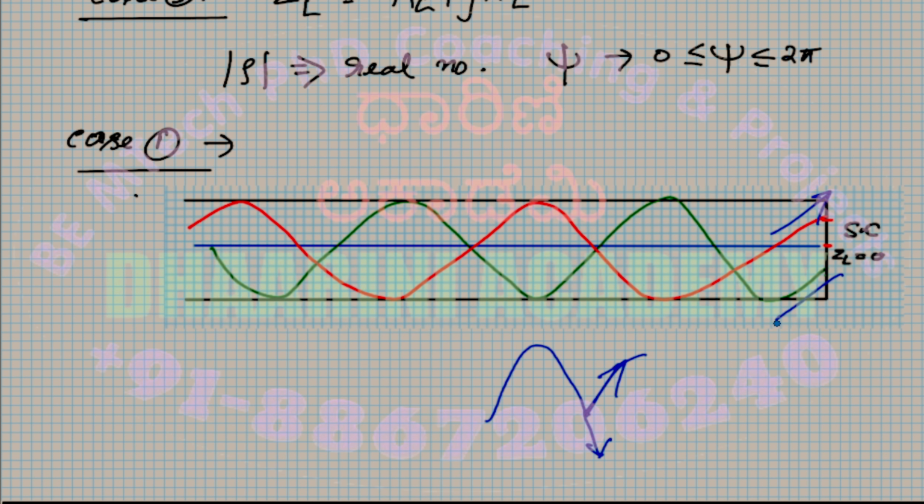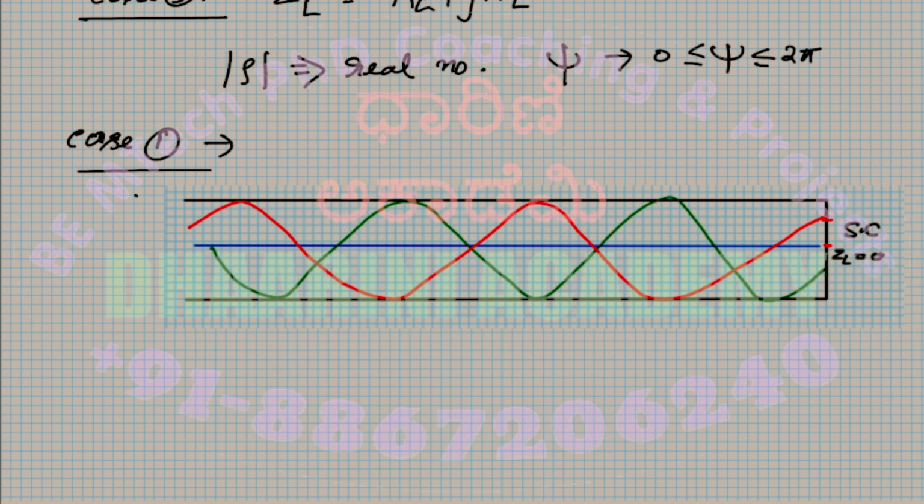Now the reflected wave goes down, right? And its position is reversed. I have a positive value, and it starts from an equal and negative. Are you okay? So that's what is going to happen. We will be visualizing this kind of waveform if you use a scope to visualize the incident and the reflected waves for a short circuited line.